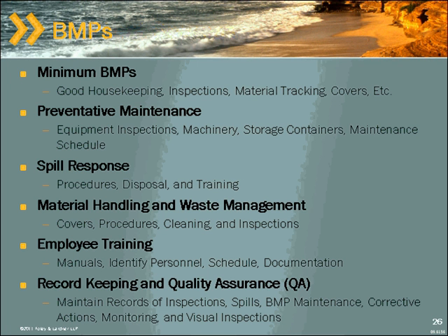Storage containers, and are they covered or not? What kind of condition? Are they on pallets? Are they located near or further from storm drain locations? And a maintenance schedule. Any spills that occur, the procedures, what the disposal method was, training to prevent spills, and all the cleanup procedures, of course.